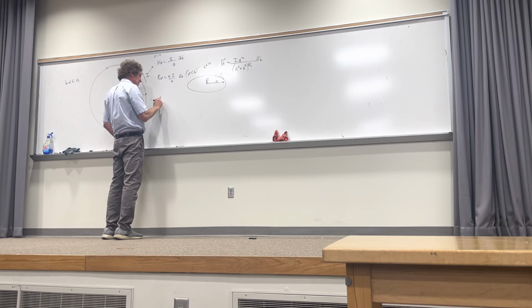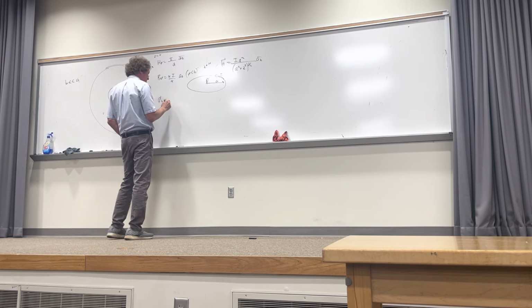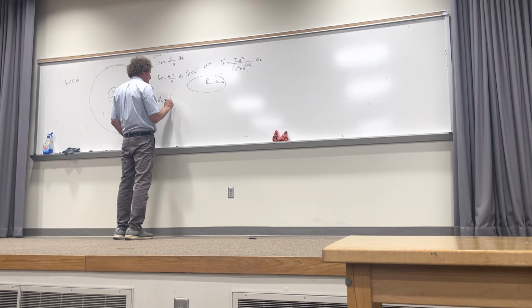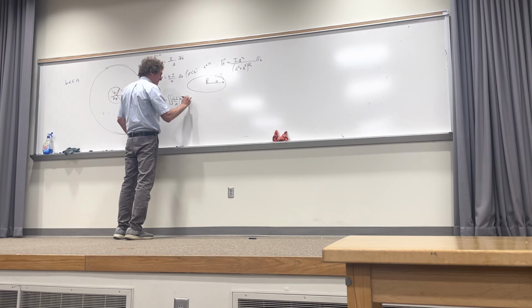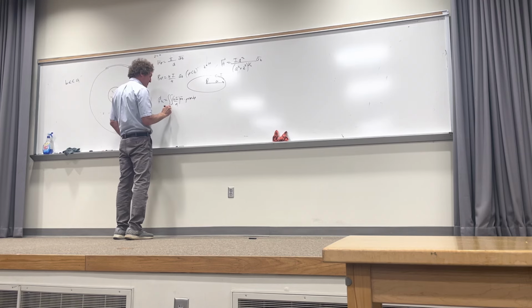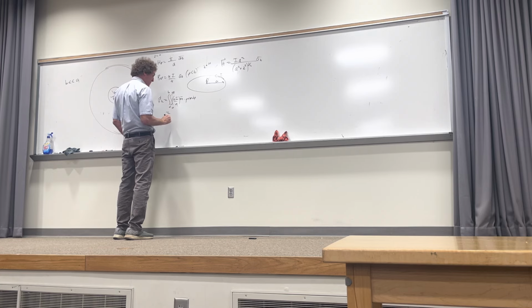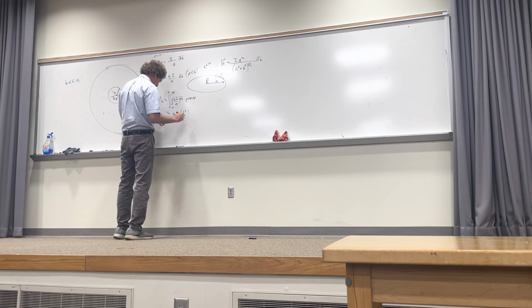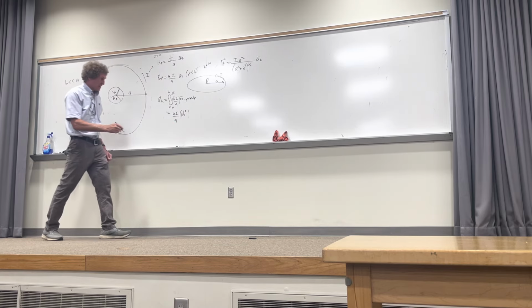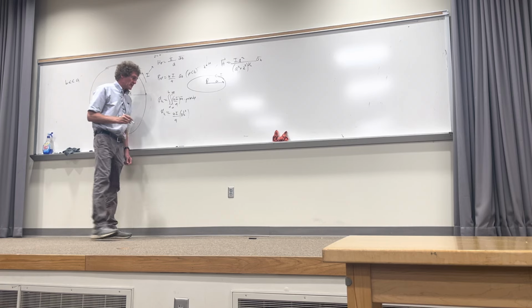Then we can find the magnetic flux through that surface, and that's going to be simply the integral of the B field, mu I over A, AZ dot ds, and the ds here is going to be simply rho d phi d rho. Phi would go from 0 to 2 pi, and rho would go from 0 to B. But what you really see here is this is mu I over A, times the surface area, pi B squared. That would be the actual magnetic flux through there. Y'all with me on this?